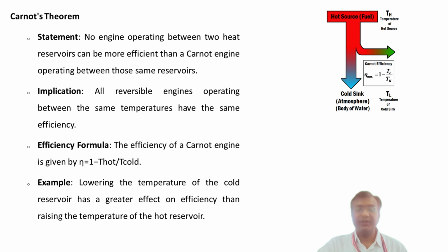Therefore, the key points for the Carnot theorem are that it states that no heat engine can be more efficient than a Carnot engine operating between the same temperatures. The efficiency of the Carnot engine is given by 1 minus Tc divided by Th. Lowering the cold reservoir temperature has a greater impact on increasing the efficiency than raising the T hot, that is the hot reservoir, for the same temperature change. The Carnot theorem provides a benchmark for evaluating the performance of real heat engines.